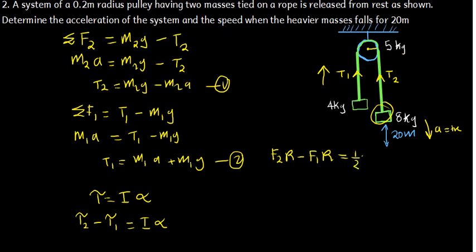The m we are going to use here, let me give it capital M, and small m1 and small m2 for the masses. So the right side will be capital M, half, substituting the moment of inertia, half M r squared, and then the angular acceleration, which is just linear acceleration divided by the radius.